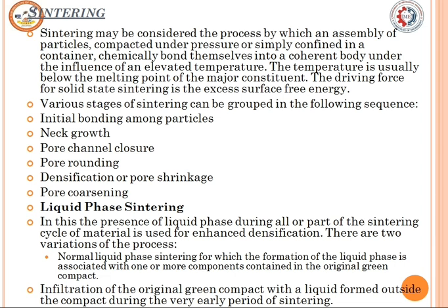Sintering is another process by which an assembly of particles, compacted under pressure or simply confined in a container, chemically bond themselves into a coherent body under the influence of elevated temperature. The temperature is usually below the melting point of the major constituent. The driving force of solid state sintering is the excess surface energy. The various stages of sintering can be grouped in the following sequence: initial bonding among particles, neck growth, pore channel closure, pore rounding, densification or pore shrinkage, and pore coarsening.